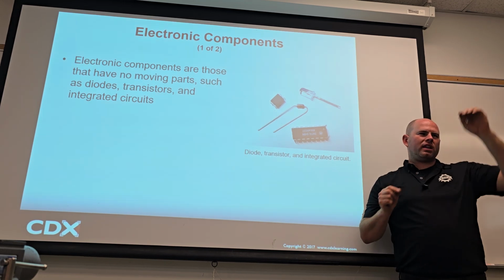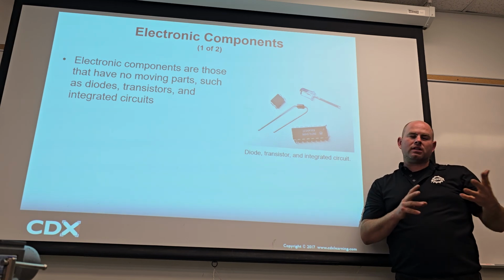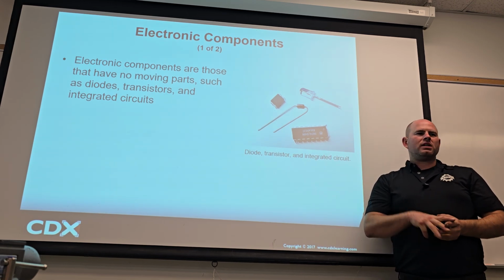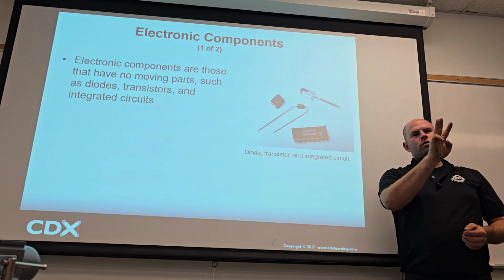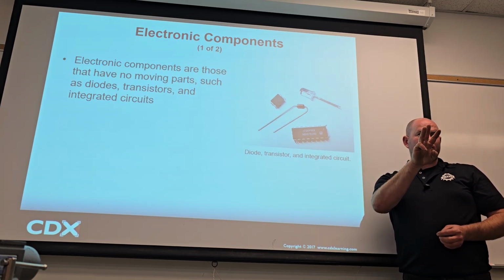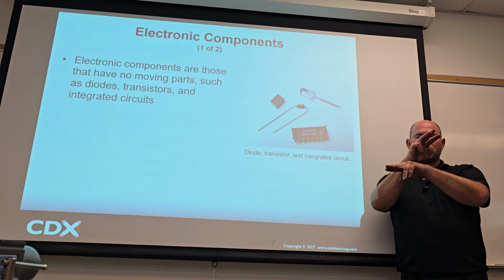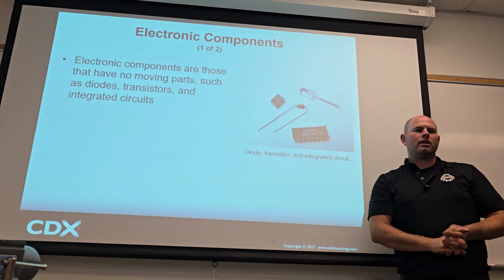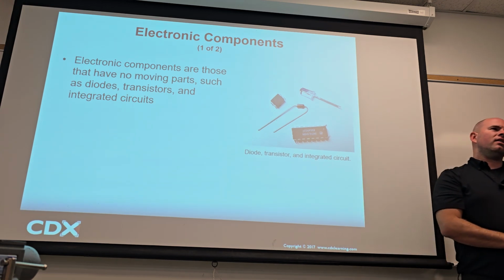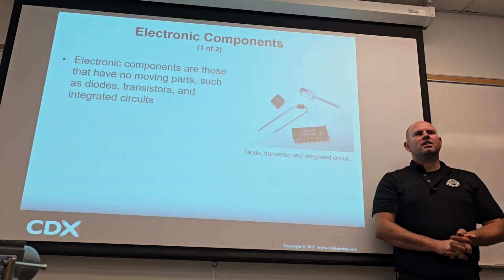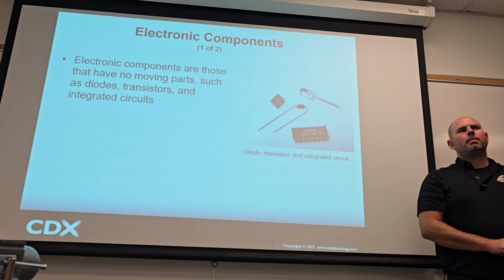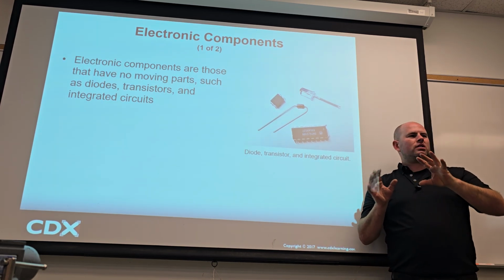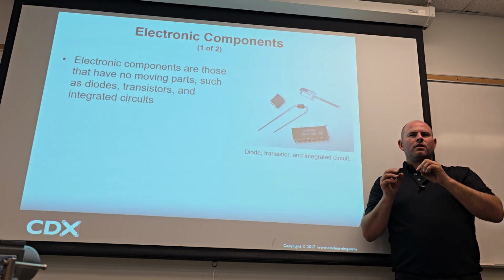Once in a great while, the ECM isn't sending the reference. Some of the sensors work on 5 volts too. But what we're doing is basically 3 wires. You can check 3 wires, and then check to make sure you get the voltage at the right points. That's as deep as the diagnosis we really have to go. And then once in a great while, you'll have something that seems like it's working, and then you'll put it in, and you might get a weird signal or a weird issue.